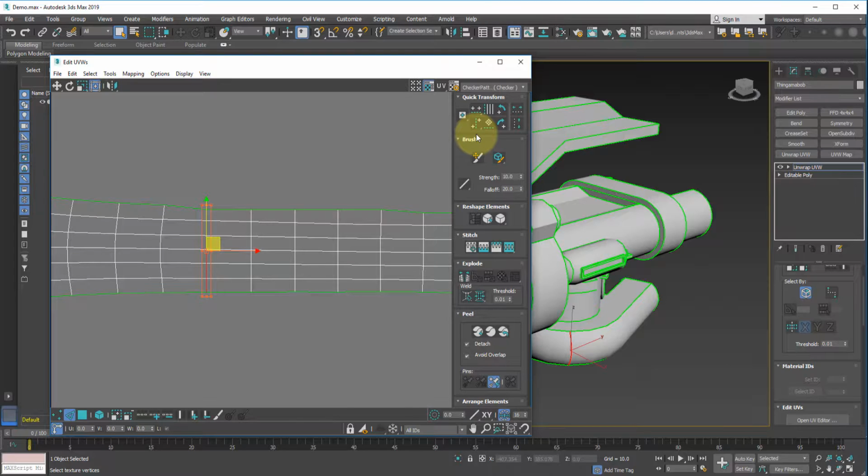Let me show you what I mean by that by grabbing a ring selection instead. So I'm going to undo this again. In order to grab a ring selection, you want to click on any edge, hold down Shift, and click an adjacent edge. Now if I go back and click on that same button, you'll notice that it will straighten out all of them individually, but keep them exactly where they were. So the alignment tools allow us to straighten up both vertices and edges as needed.